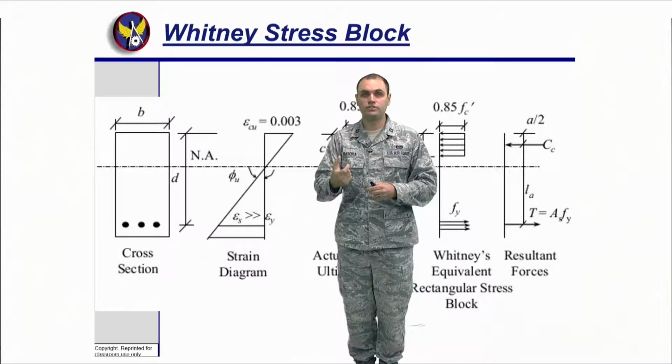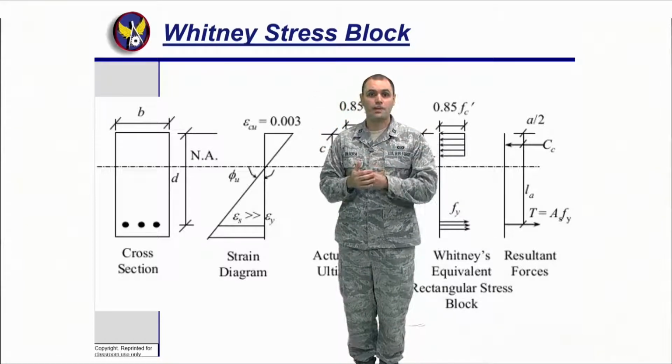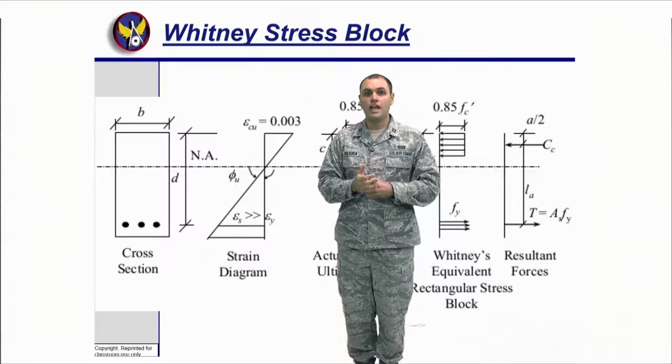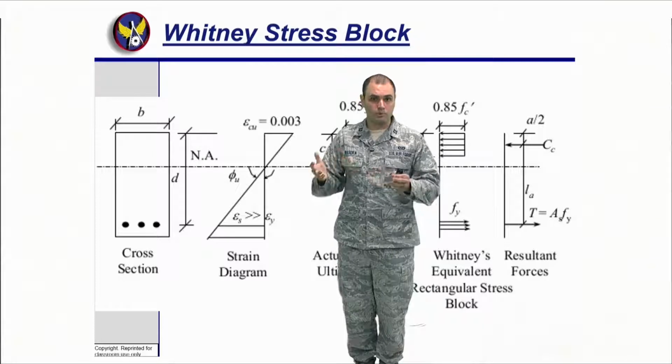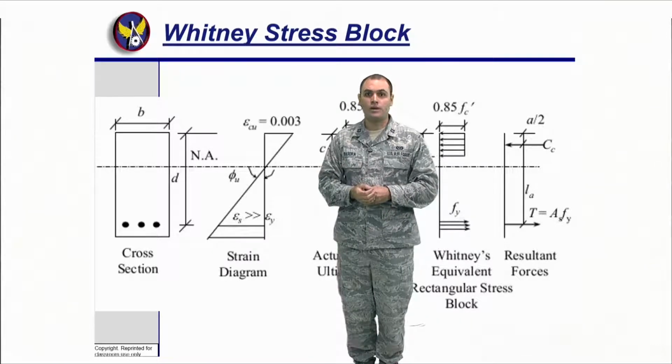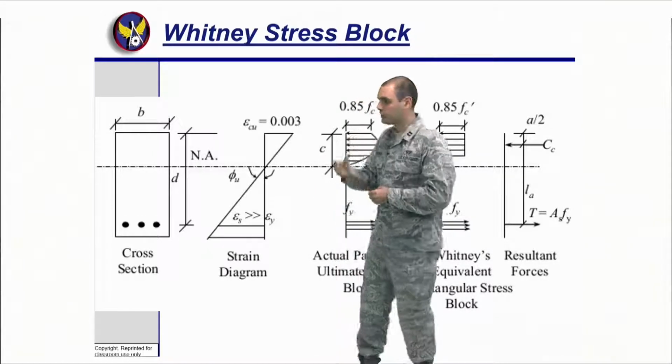Because if the steel yields, that means I start seeing cracking in my concrete. That means I have time to escape my building. If my concrete yields or breaks, a brittle failure first, I would not have time to escape my building. That's what's going on here.